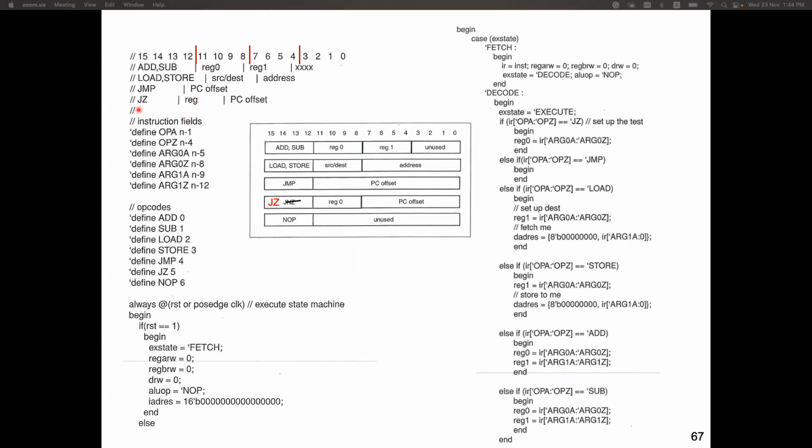Jump if 0, J0, checks the value of the register with this address. Bit 11 to 8 contains the address of this register. If this register's content is 0, then it will jump by the offset given in bit 7 to 0. Otherwise, the jump will not occur.